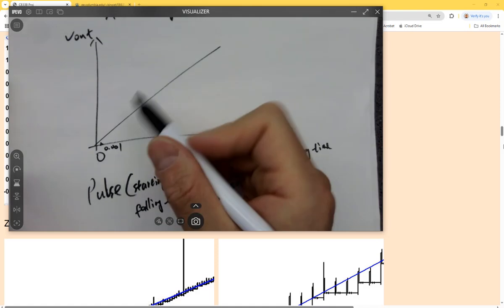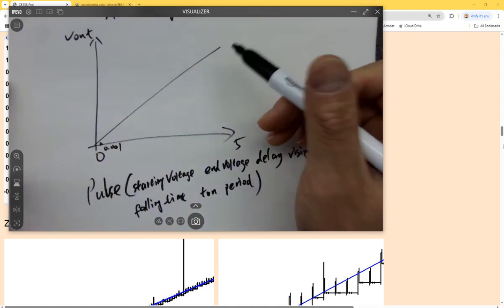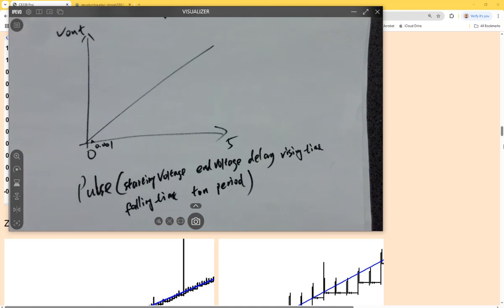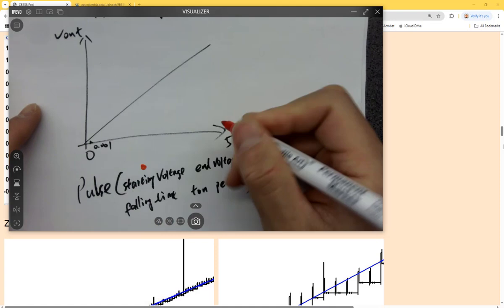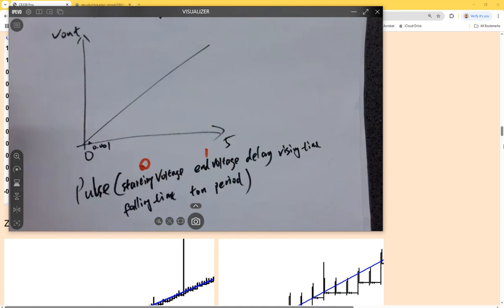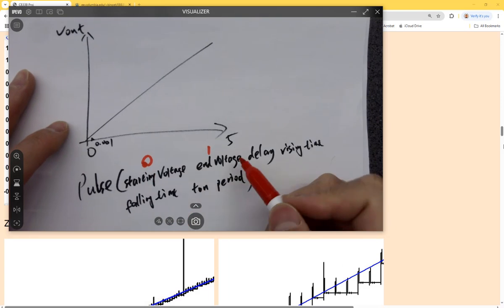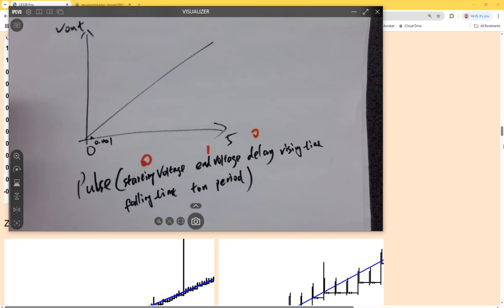So in order to form a linear line like this, what you can do is set up a pulse function, but never run a pulse. Do a pulse function starting from 0 volts to 1 volt, because this is the 1 volt VDD. Just keep in mind it's not 5 volts, but you guys are going to use 3.3 volts, I think. Anyway, just logic 0 to logic 1, and time delay doesn't matter, just 0.